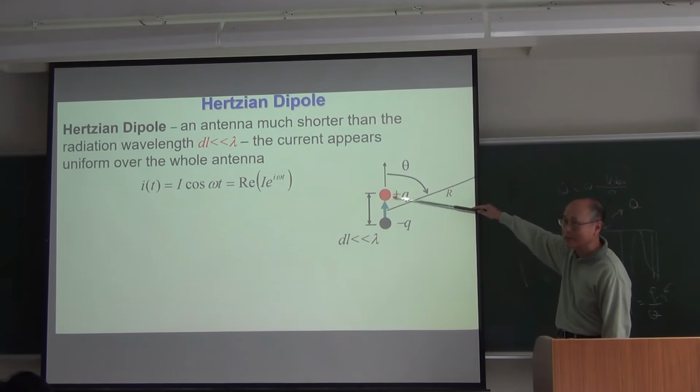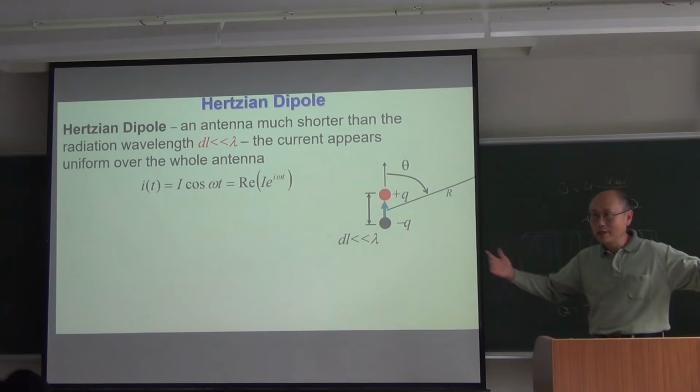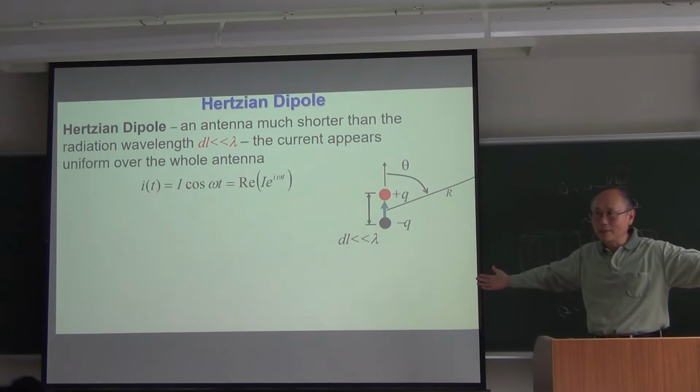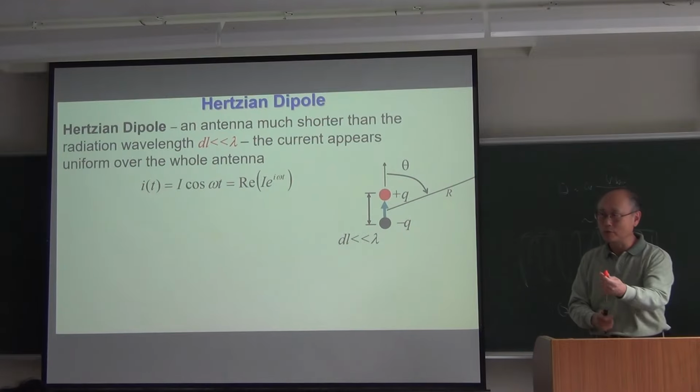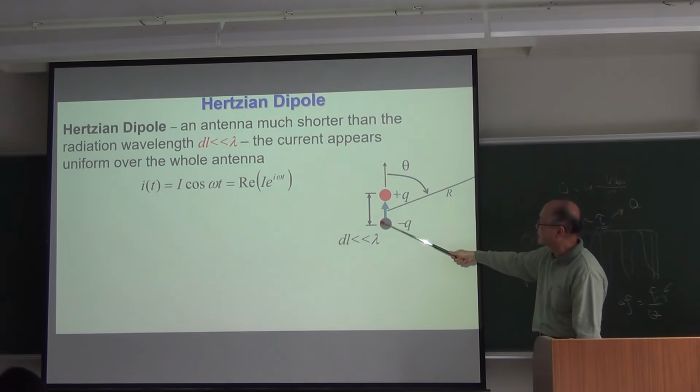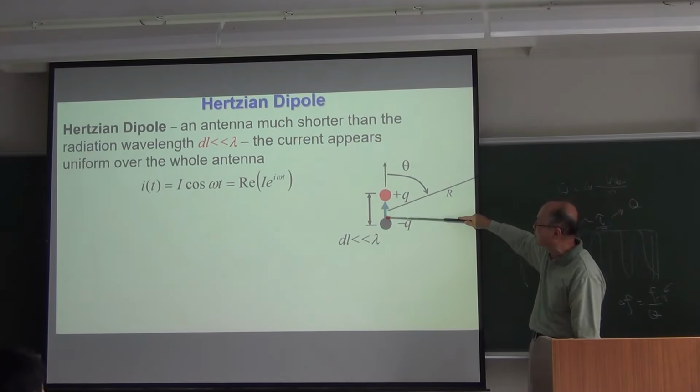Okay，这是一个 antenna。然后呢，你辐射的波长远大于这个，所以这是一个 lumped circuit，或是一个 transmission line circuit。lumped circuit 的意思就是说，你的这个电路的 dimension 远小于你的电磁波的波长，所以所有东西你不需要太考虑它的相位。同样的，在这上头我们不考虑电磁波的相位。Okay, just treat it as a uniform current oscillating with time, but there's no spatial dependence on it.